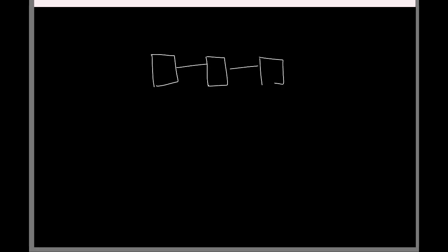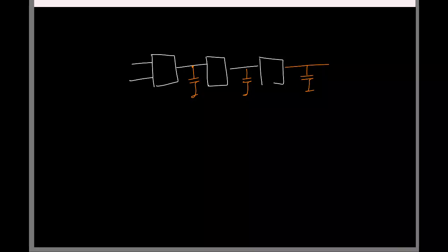But now here again you will have the stability problem, and here it will be even more pronounced because you have 3 capacitors. So again, to stabilize it, you have to do some kind of compensation. And you can use Miller compensation for our help. And there are a couple of ways in which we can do Miller compensation here. And one way to arrive at a 3-stage Miller compensated OTA is by following.